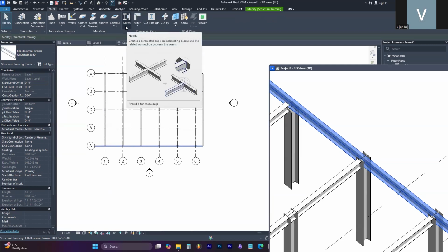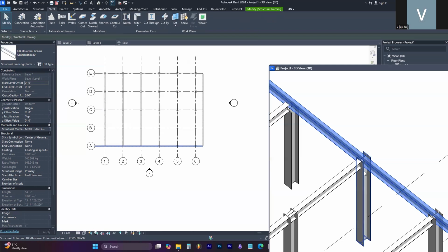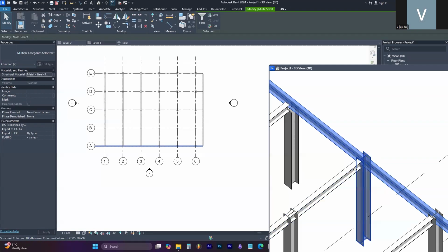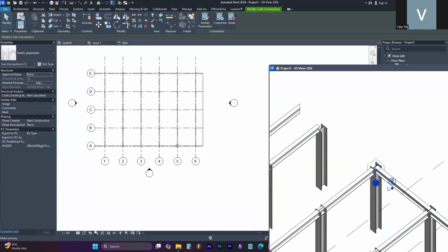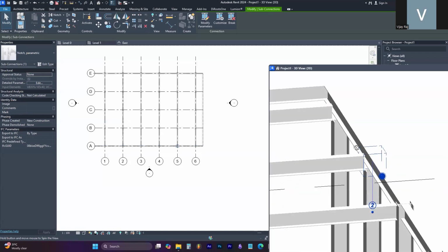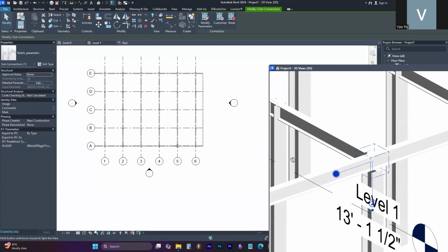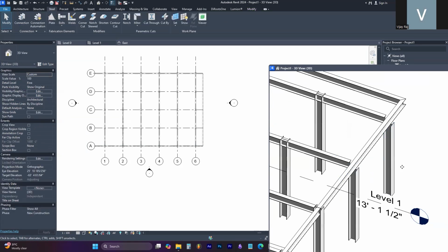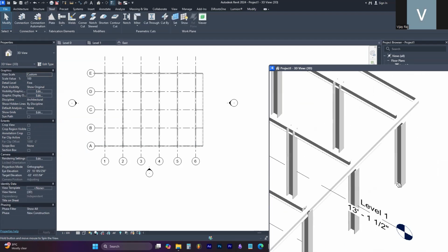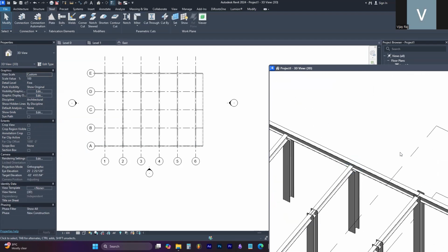It's also called coping. For coping, you select the elements you want and go to the steel option. You can do the notches. You can get it terminated like that. And if you swap these things, you can get your primary and secondary options. As simple as that. Okay.